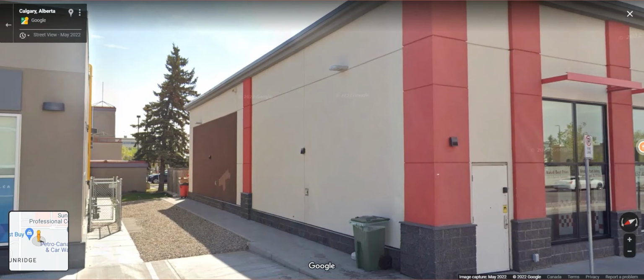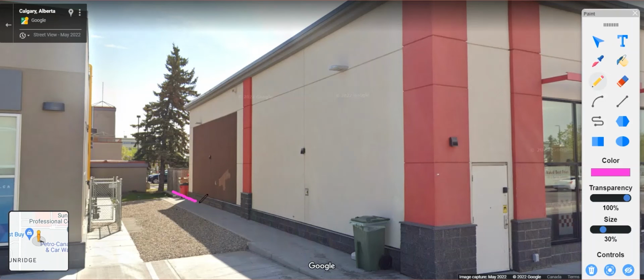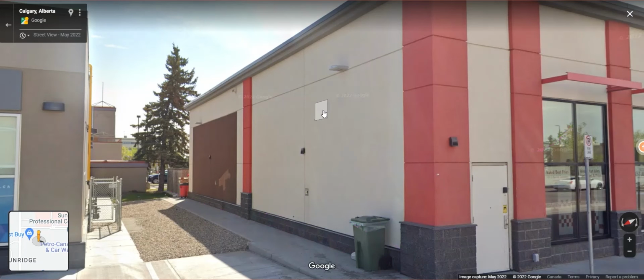Originally I had shown a concrete block wall here because in this case, there was a sidewalk there, but the property line was actually right against that building face. But what was unique about this was that the client owned this site and owned this site. So there's still a property line there, but he owned both sites. So this wasn't really an issue. I don't think it was a good decision to not do the concrete block wall, but nonetheless, we were able to do this, and I'll show you how that was possible in the code.